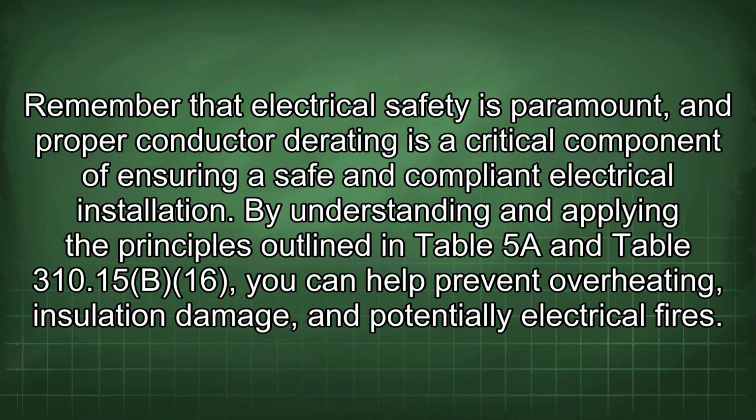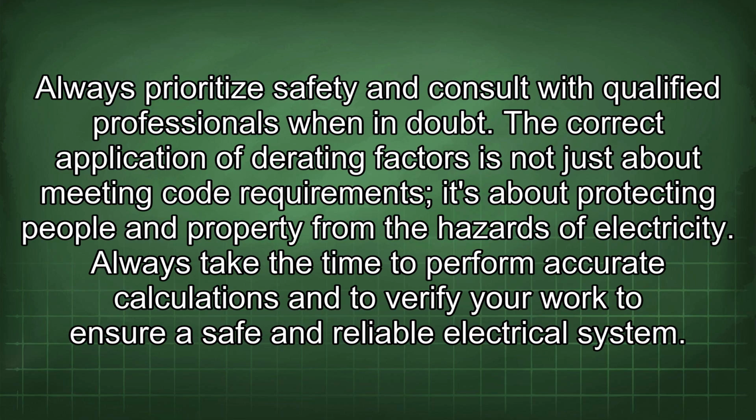Remember that electrical safety is paramount, and proper conductor derating is a critical component of ensuring a safe and compliant electrical installation. By understanding and applying the principles outlined in Table 5 and Table 310.15(B)(16), you can help prevent overheating, insulation damage, and potentially electrical fires. Always prioritize safety and consult with qualified professionals when in doubt.